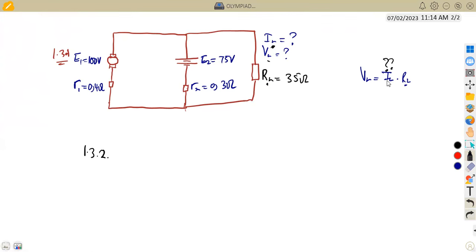All right. So like I said, the first thing that you're going to need is to introduce a branch AB across the load resistor. So you're going to short this load resistor. So our circuit is just going to be like this.